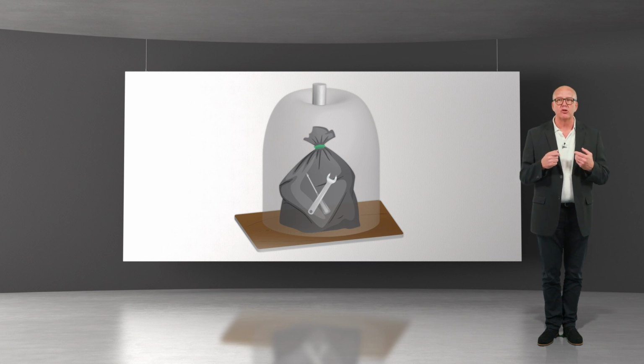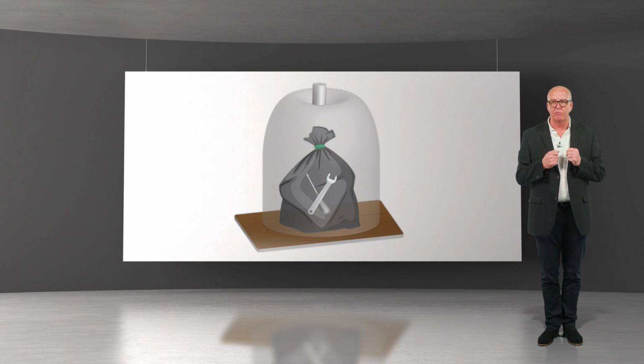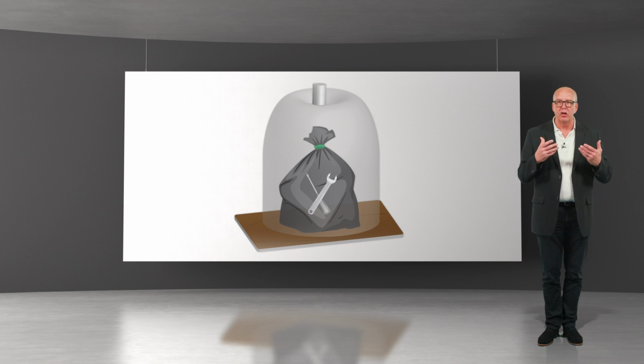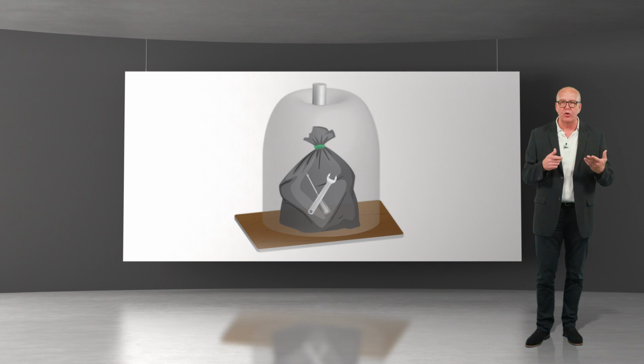The site should be in a location where the subsoil is as dense as possible. This protects the soil and groundwater against leachate emissions. The ground should not be very permeable. There should not be groundwater nearby, and it should be able to absorb liquids if leachate emissions do occur.